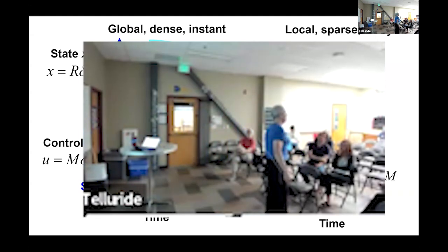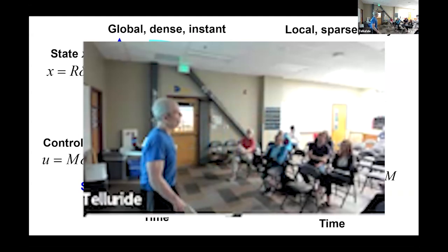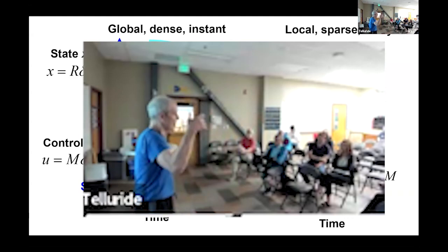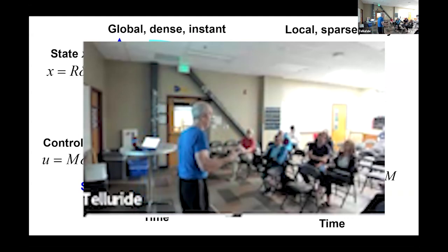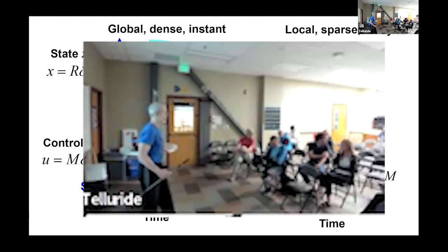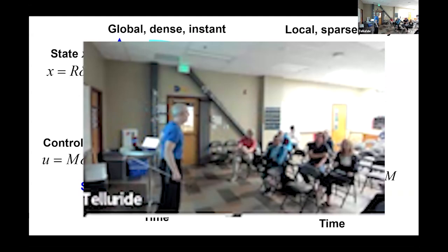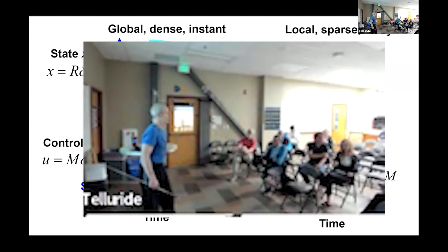Well, the nonlinearities are usually going to be saturations. Okay, but those are the ones we care about. There are two kinds of saturations. I can only go so fast, and if I hit the wall hard enough, I die. So these are hard limits, right? And those are the things that matter, and those are the things that MPC is best at. So you can put all that in there. Also the nonlinear dynamics, right? There's a lot of nonlinear dynamics, fundamentally nonlinear. Any kind of chemical plant is exponential in the products of the reactants and stuff like that. Those are also the nonlinearities that people care about, right? It's not all just small signal controls for stability.